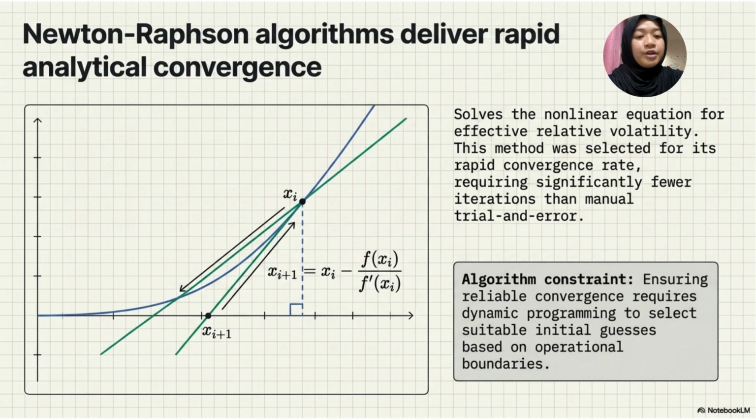Ultimately, our numerical processing is governed by classical chemical engineering thermodynamics. The system calculates relative volatility, alpha, to establish the ease of separation, uses the Fenske equation to determine the absolute minimum theoretical stages required, and finishes by evaluating the overall tray efficiency, E0. This benchmarks the real-world performance of the column against theoretical perfection, giving plant operators immediate actionable data.